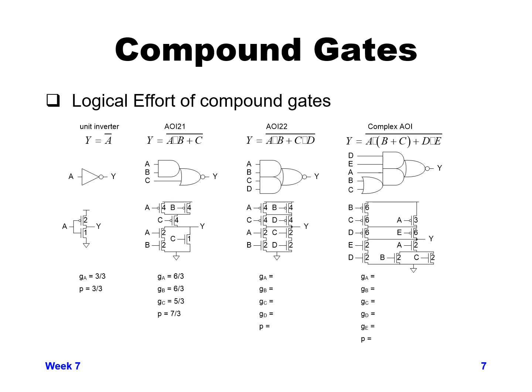So let's go through the other two. If you want to pause here real quick and try to figure out what these values are for the other two, pause, and then I'll go through it myself. So now that you've paused and figured out each of the other inputs for the other two gates, the logical function for the next one is the one that we've been looking at for the previous few examples, A and B NORed with C and D.